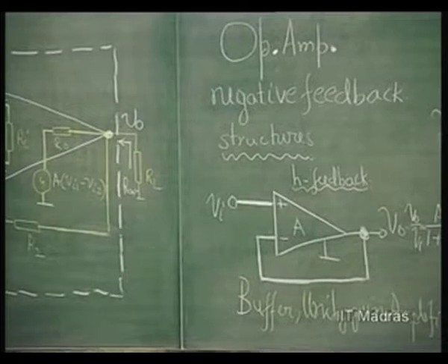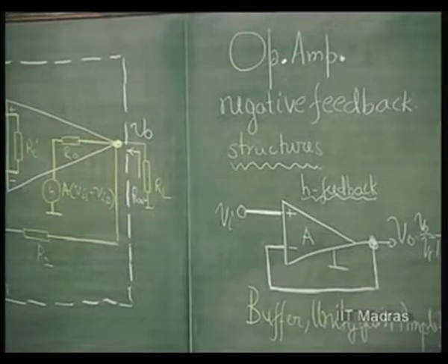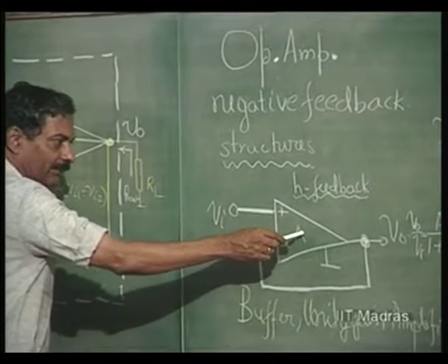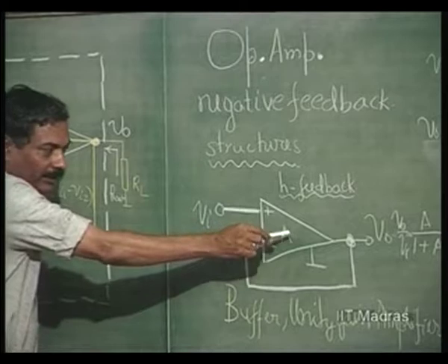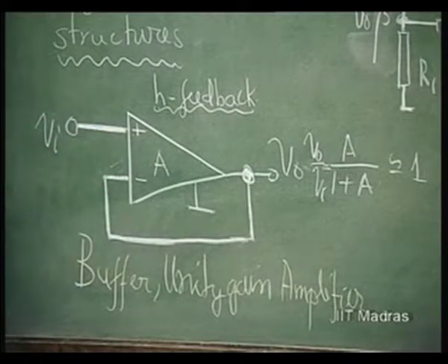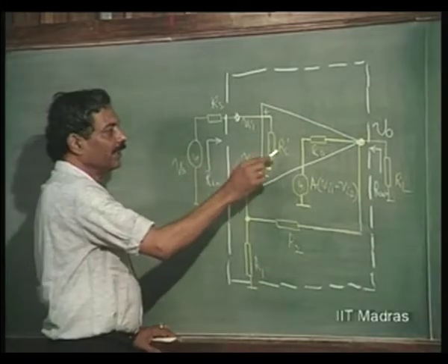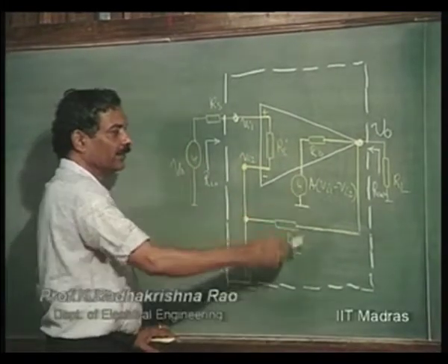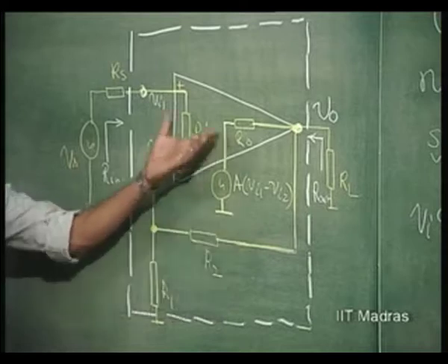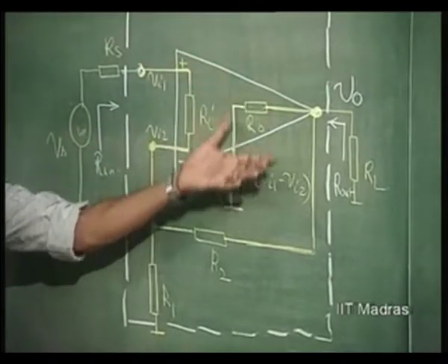So, now we will go into the 2-port parameter technique that we have used. Now, we will introduce all the non-idealities associated with the op-amp. First, we said op-amp is a structure with a very high forward transfer parameter. So, A was tending towards infinity. In the G matrix of this, the other 3 parameters were 0. But now, the other 3 parameters are not 0, they are finite. That means finite input impedance, finite output impedance, and finite non-infinite gain. Such an op-amp equivalent we can get for any configuration of cascaded amplifiers. This we know how to obtain.